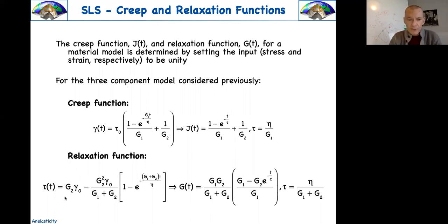On the other side, if we want to write the stress as a function of strain by a given modulus, so tau of t is a function of the deformation of t, that is the general stress, or if you want the modulus, you can write it. And now you see it's made by different terms, and everything will depend on eta. So eta is a sort of a time messenger that is deciding the reaction on short time scales and the reaction on long time scales.